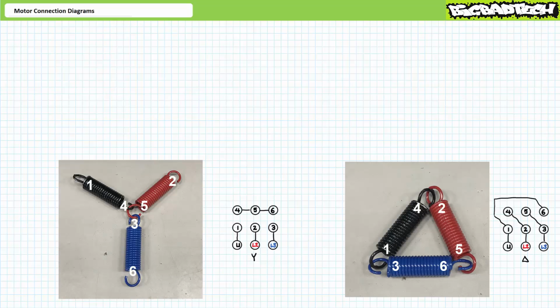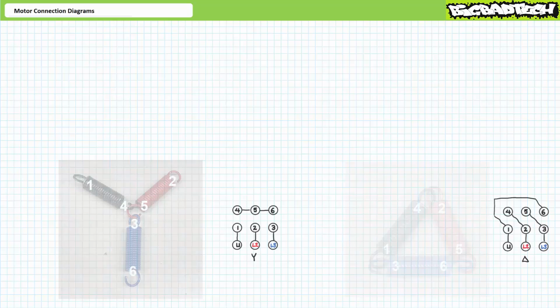You might initially think that any end of any winding will do equally as well as any other, but they don't, for a rather important reason. You'll no doubt recall that current direction influences magnetic polarity. Connected in this improper fashion, winding 3, 6 would be a north when it's supposed to be a south, and vice versa, hopelessly wrecking any chance of establishing a smoothly rotating magnetic field in the stator. Follow the connection diagrams exactly as illustrated.